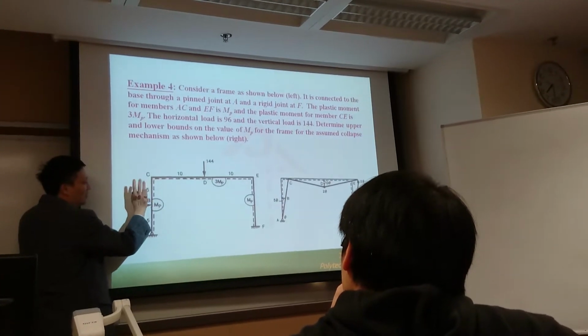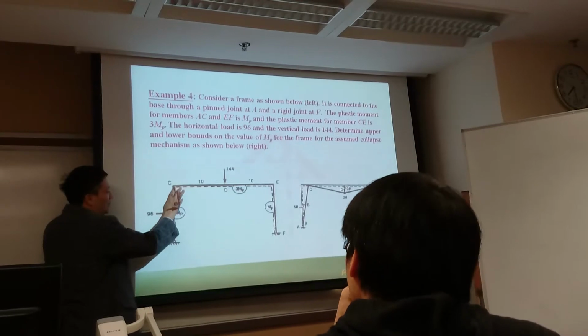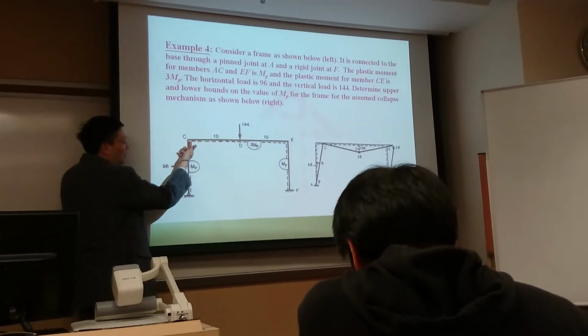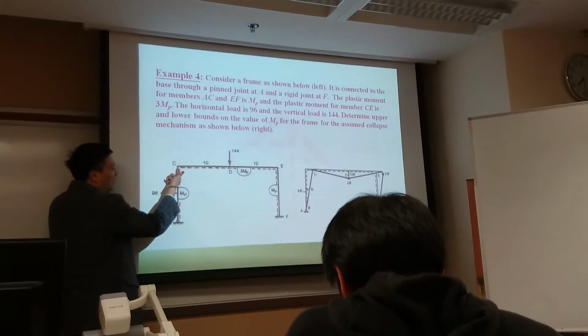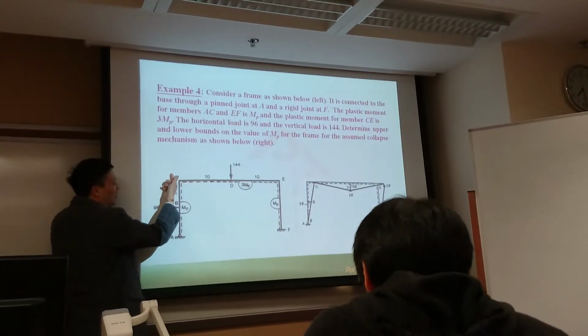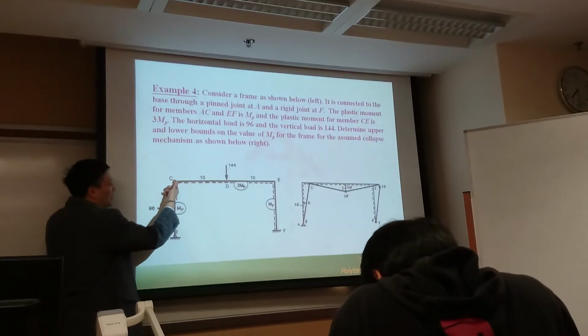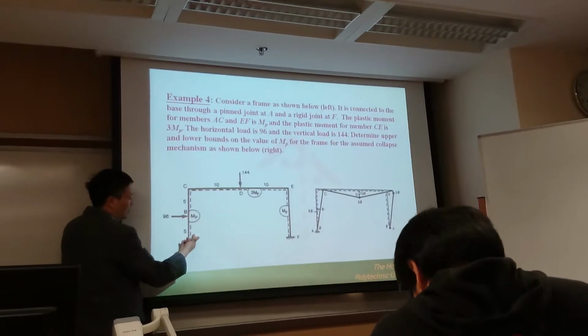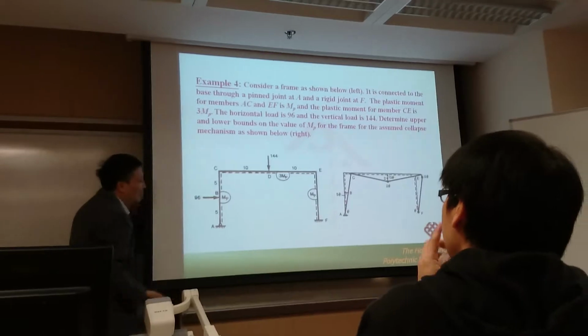This is not a plastic hinge, but we know the moment. So we can replace this section by one hinge and the obtained moment MC value. So we can introduce a virtual displacement like this.